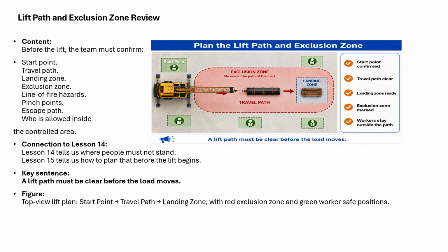Lifting path and exclusion zone review. Before lifting, the team must confirm the start point, travel path, landing zone, exclusion zone, line of fire hazards, pinch points, escape paths, and who is allowed inside the controlled area.